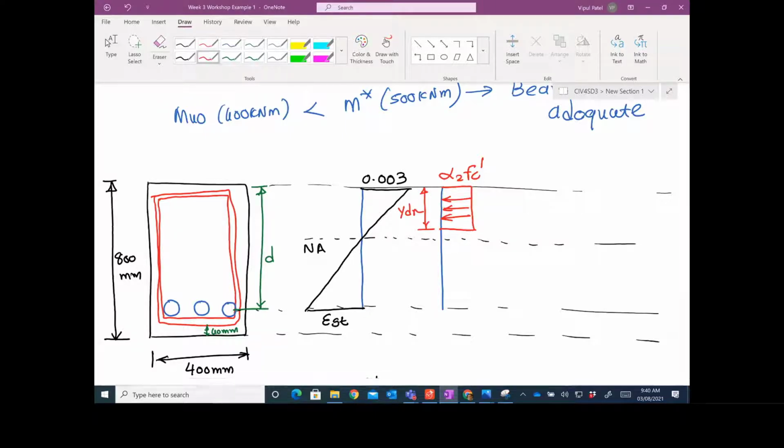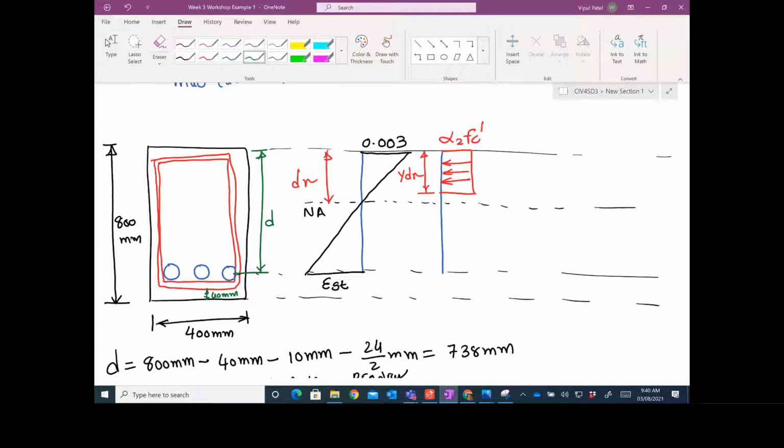By the way, dn is this one, the depth of the neutral axis. And then you will have this tension force. Let's put the green color on the tensile stress, which is, let's say, sigma st. And let's put this sigma cc, the concrete compression force, in red. Concrete tensile force going left to right.